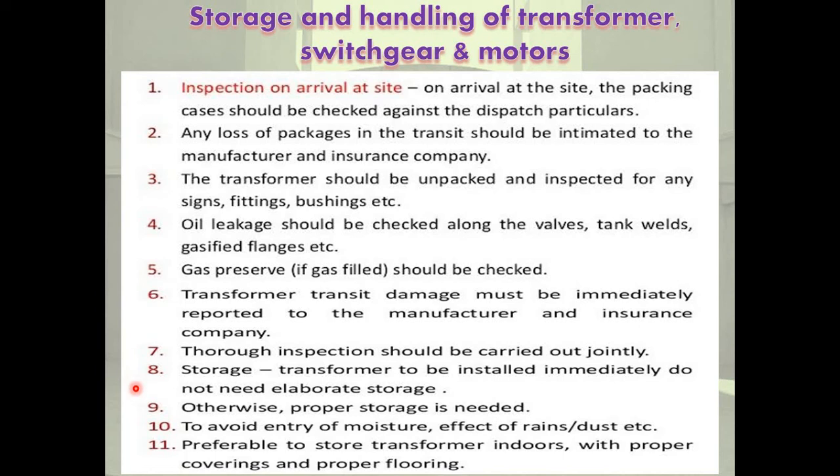A transformer to be installed immediately does not need elaborate storage. Otherwise, proper storage is needed to avoid entry of moisture, effect of rains, dust, etc. Preferably store the transformer indoors with proper coverings and proper cooling. The relative humidity of the air in the storeroom should not be more than 68%. The temperature should not be below plus 15 degrees Celsius.